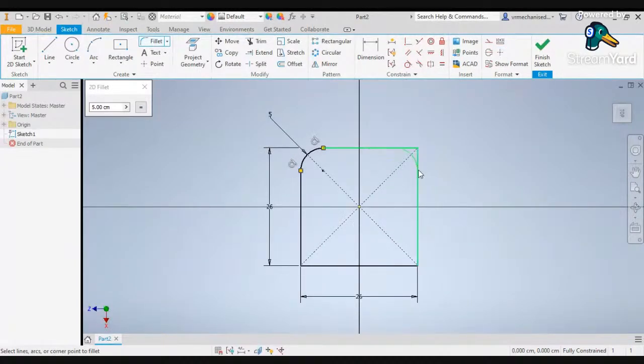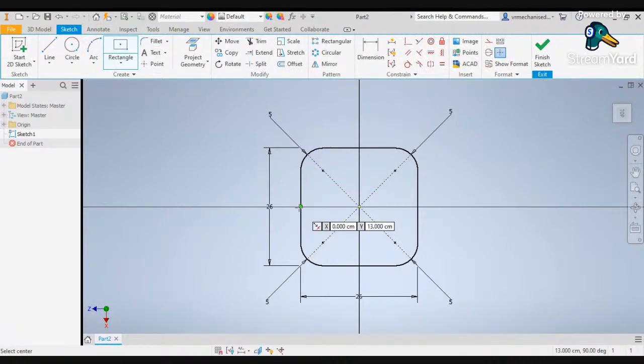And again for the next option, same. We'll be doing it for all the four sides. Once this is done, you can see that the corners are also nicely filleted. And now we need to add slots for placing the tires and the motors, right? If we want to make the mountings, we need to create cuts over here so that these cuts can be converted into the mountings later. So we'll draw that from the middle point.